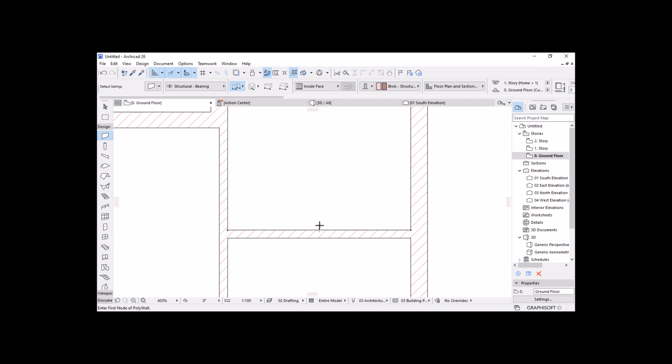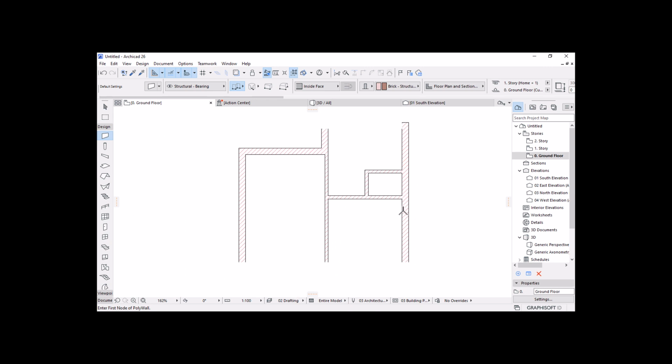Okay, and then I'm going to use this midpoint of this wall. You could see the midpoint by this dash, or by this vertical line, and then normally to reference it with these 2 points to show the length of that midpoint, right? And then I'll click on it, and then going up by let's say 1.2, then hit enter. Then we go on the right side horizontally and then click to complete it by this wall. We could now right click to OK to complete that. Okay, so we have that there.